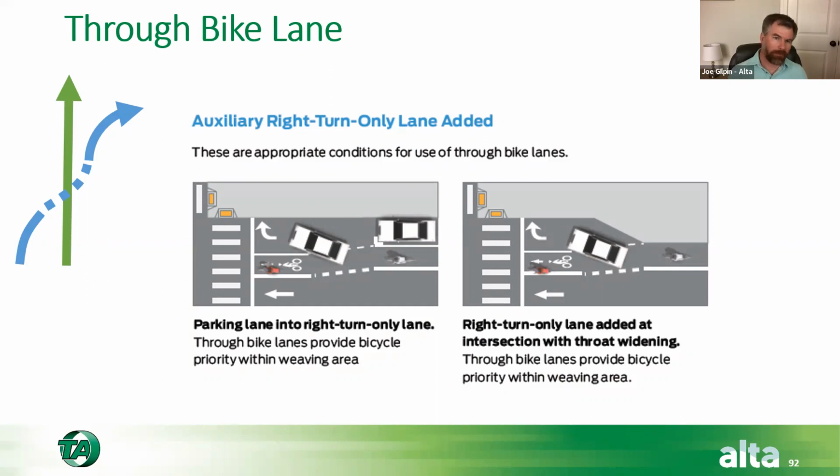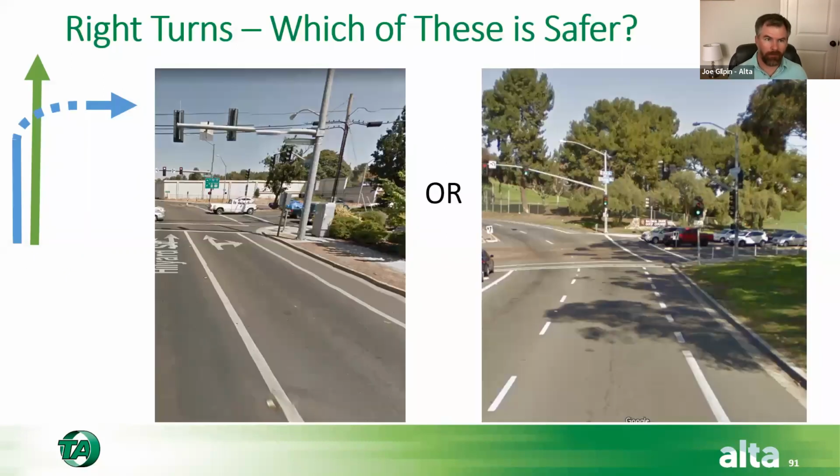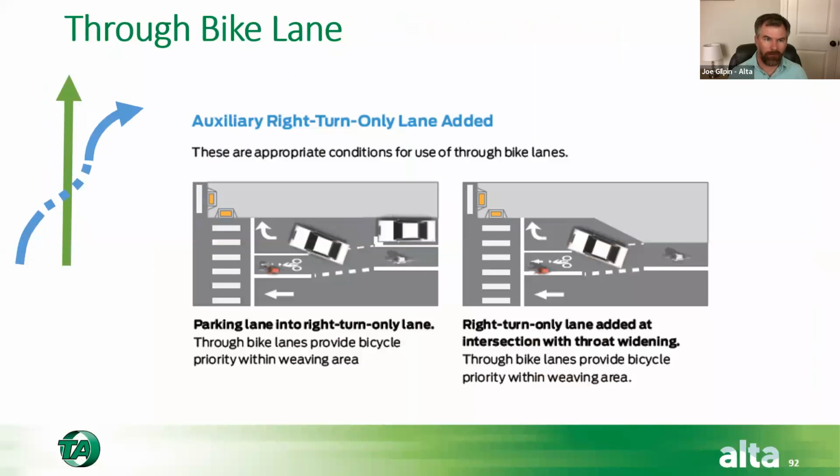So then the comment that I believe Karen made a few minutes ago, about getting the bicyclist to the left of the right turning motorist, is what we typically try to do, and this is a bit different, right? So we're going from motorists getting in line with or crossing across the bike lane here. We're now having the motorist cross completely over the bike lane and then get into their own space and make the turn, and so again, we're moving that conflict point in advance of the intersection.